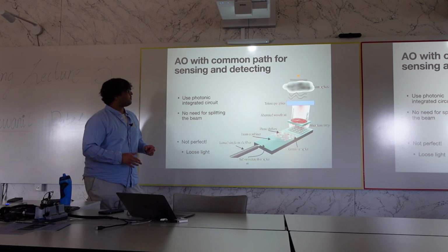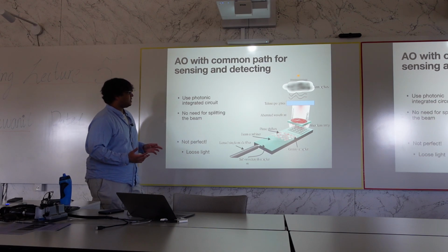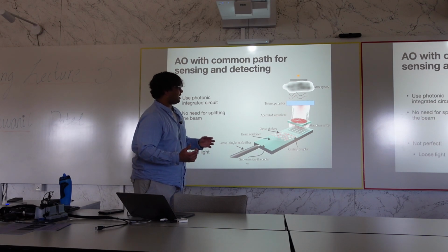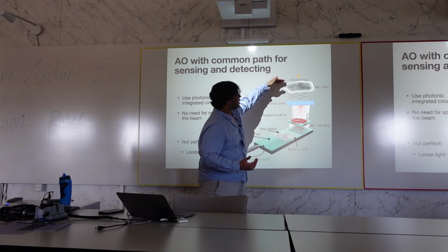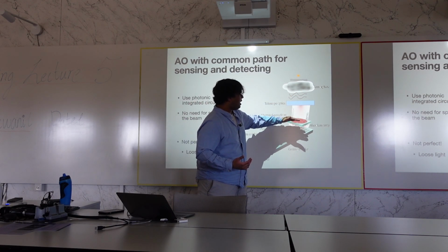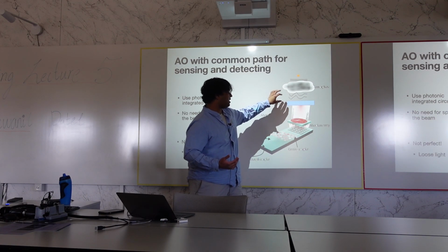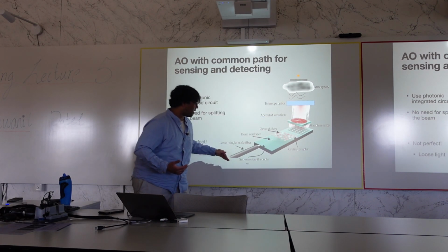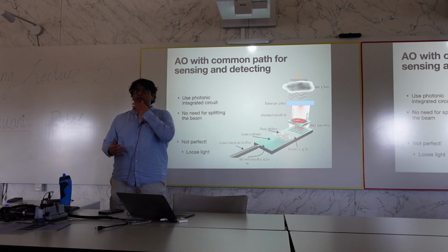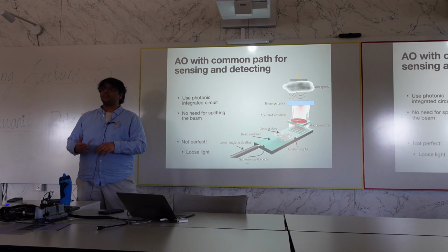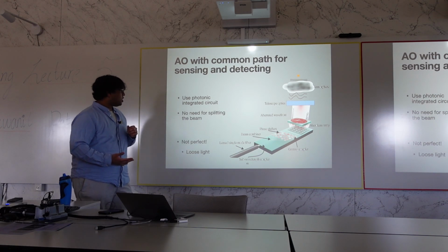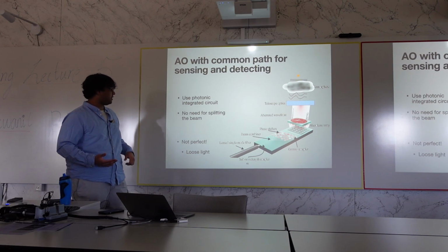I worked on simulating a photonic chip which sits at the focal point of your telescope. So you have your light coming in from the star, it gets emitted by the atmosphere, you have aberrated wavefronts, it goes through the telescope, and if you feed this light from the telescope into the chip, it basically corrects for the atmosphere, and you can efficiently use the light without splitting. So essentially this way of doing adaptive optics, you don't need to split the light, and it uses integrated circuits.